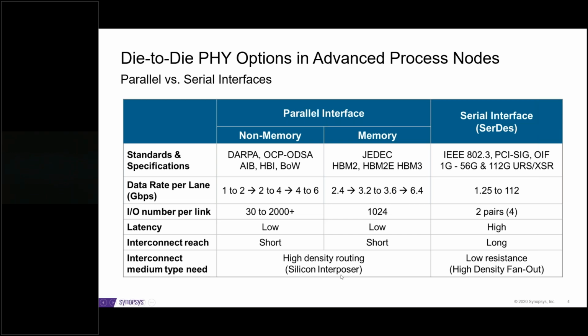So that points to the silicon interposer. And then, of course, the serial not needing that many wire interconnects would be able to cater to a much less dense environment, but still, depending on the wires and the number of devices you're integrating in a package, you would need different levels of density, but maybe not as dense as the silicon interposer would provide.